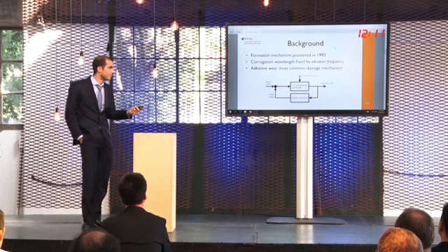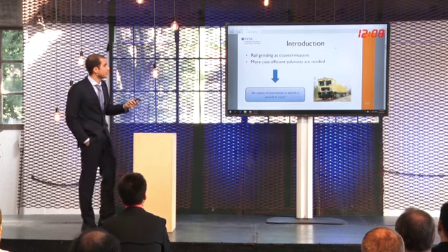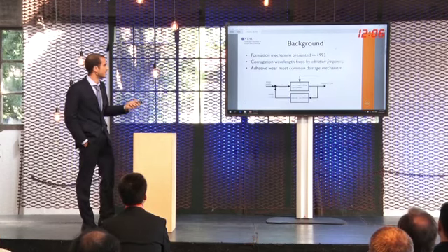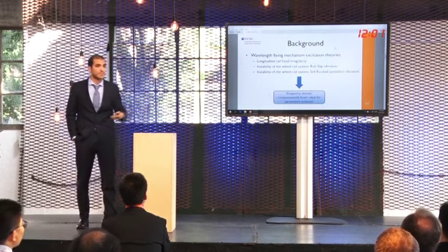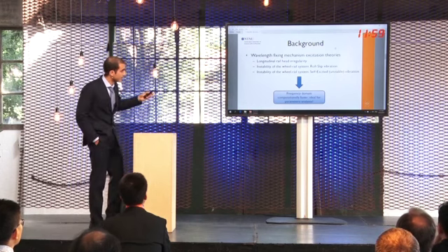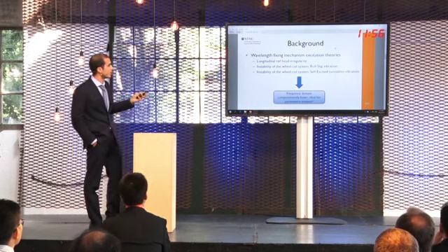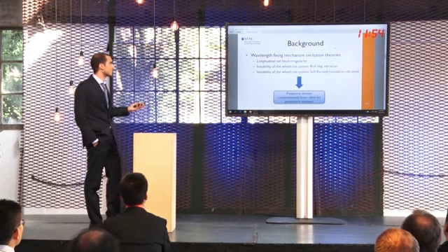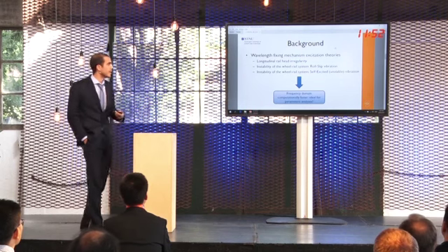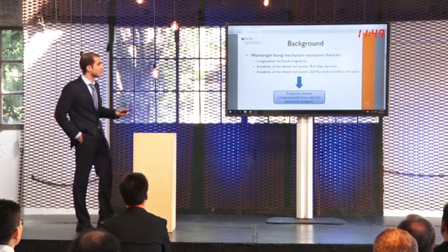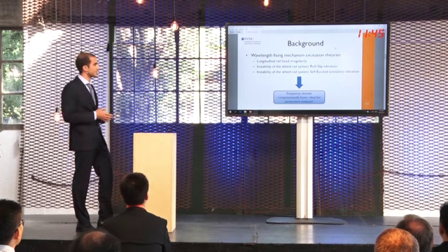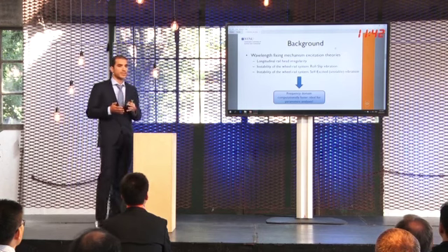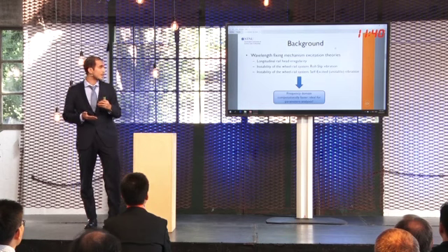In order to excite the system, there are actually a lot of excitation theories, two mainly. The first one considers the longitudinal rail head irregularity as excitation method, while the second one considers the instability of the wheel-rail system in particular situations, for example, when the contact forces are near saturation.